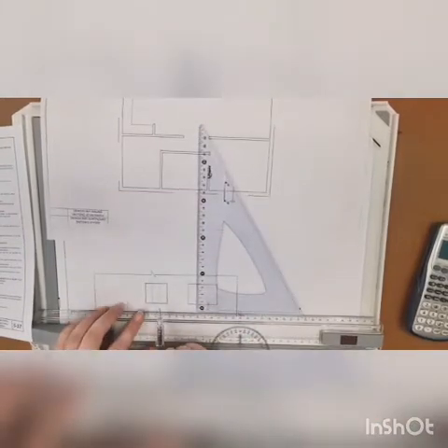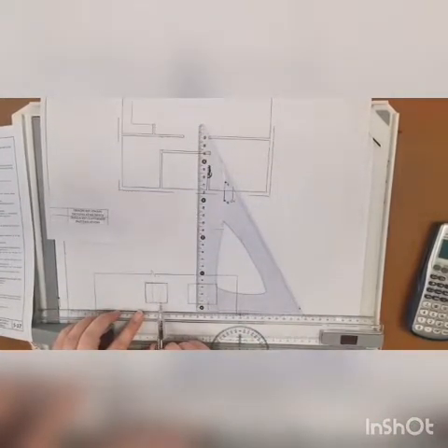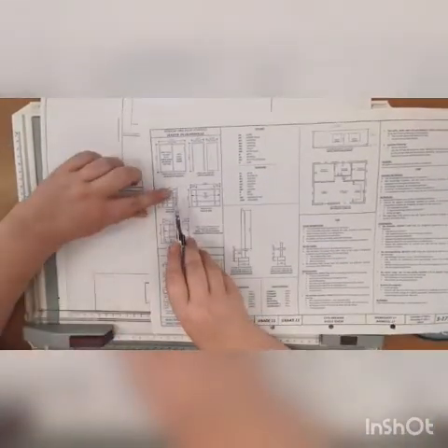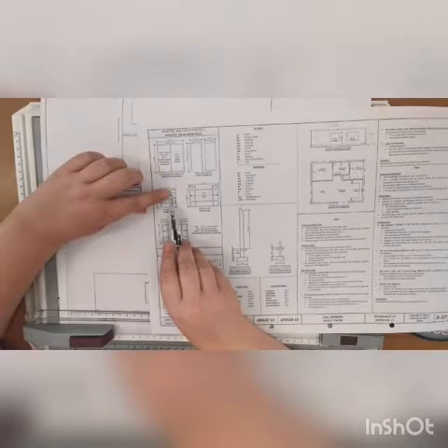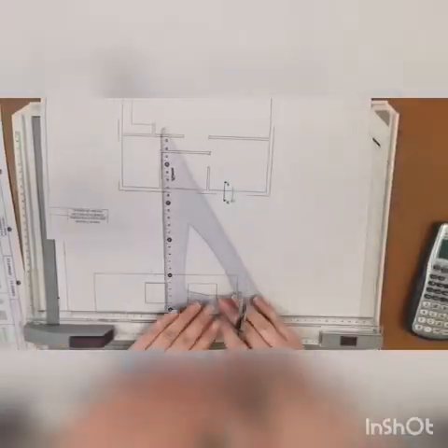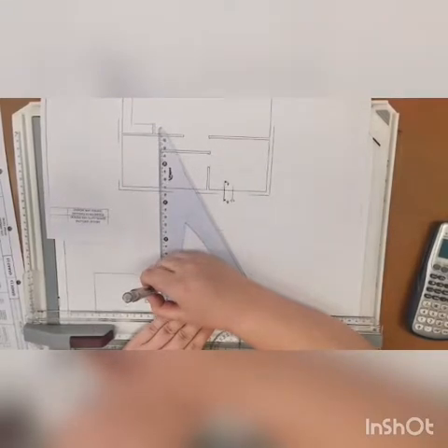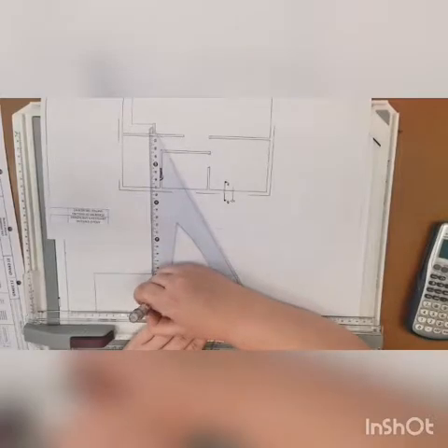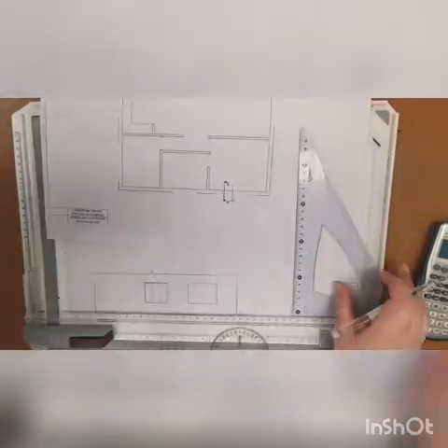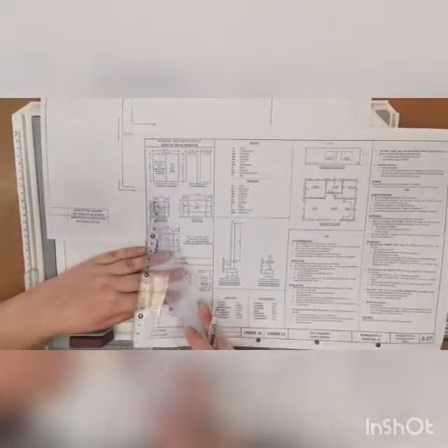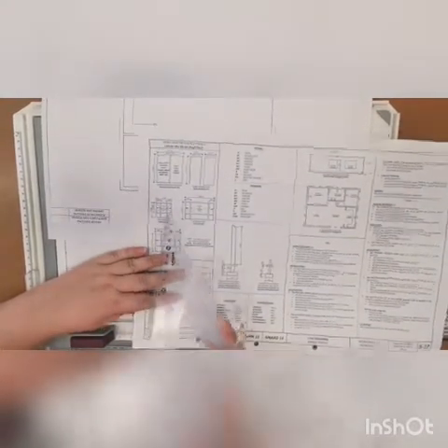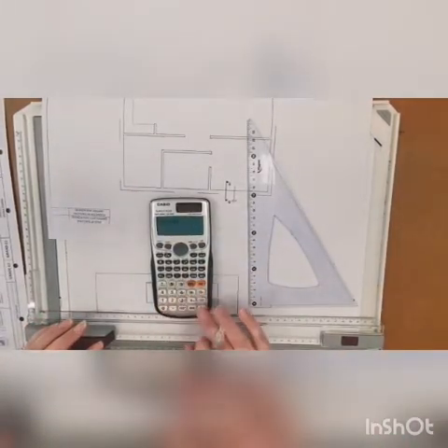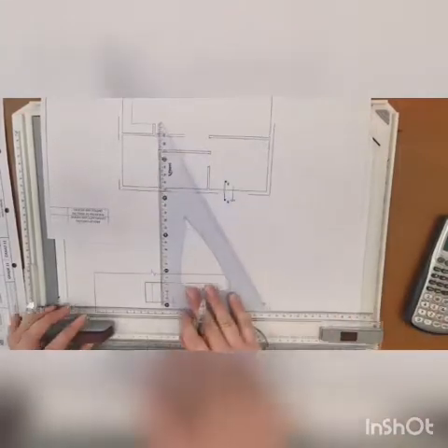Okay, now I don't put my frame inside those, I put it inside that side, because if you look here, the measurement goes to the outside of that. So we move inside to do the frame. I'm doing this all lightly because I am going to have to do a little bit of erasing. Then from the top 1,000 down to that inside line. 1,000 divided by scale gives me 20.